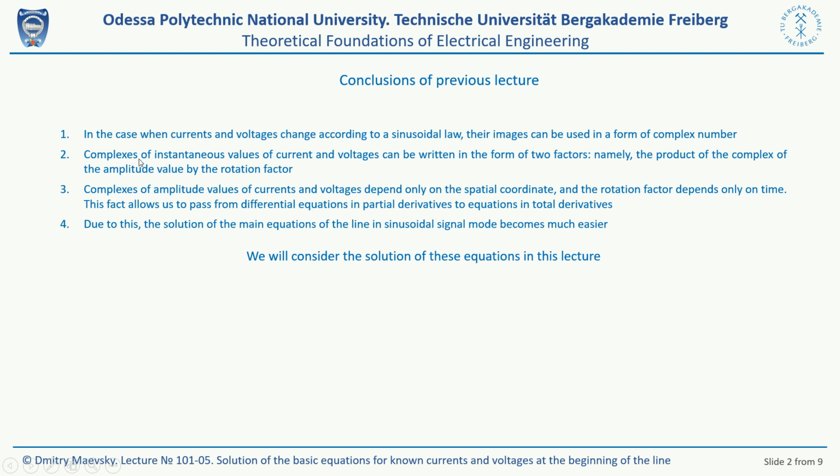We note that the complexes of instantaneous values of current and voltages consist of two parts. The first part is the amplitude value complex, which depends only on the spatial coordinate. But the second one is the rotation factor, which depends only on time. This allowed us to move from a system of partial differential equations to the corresponding system in total derivatives.